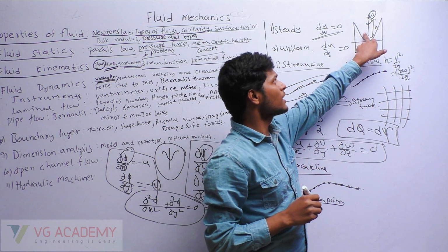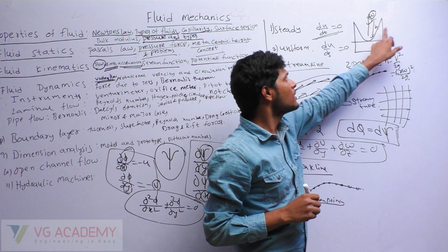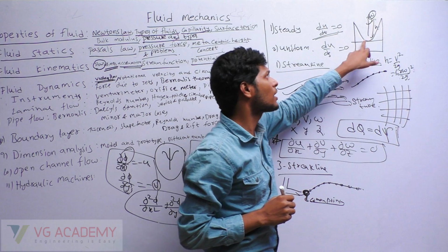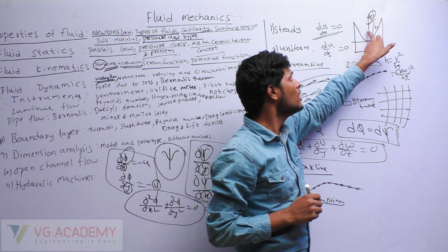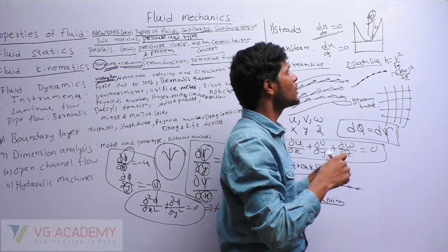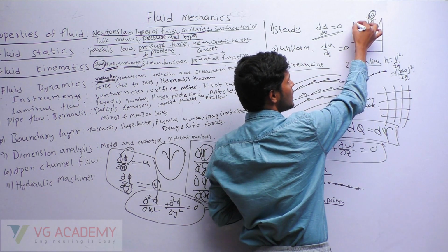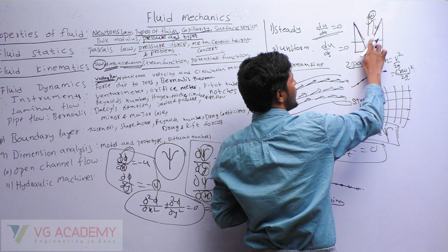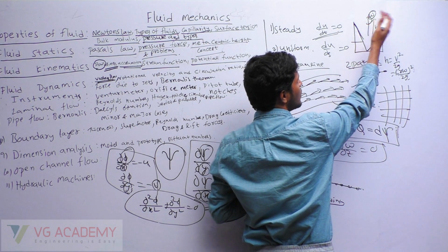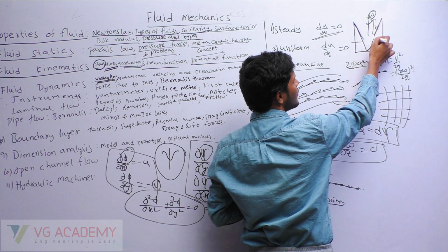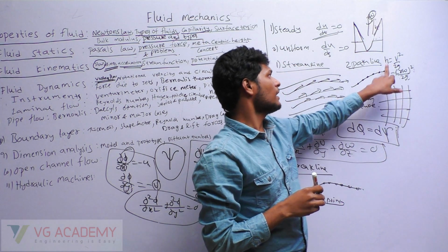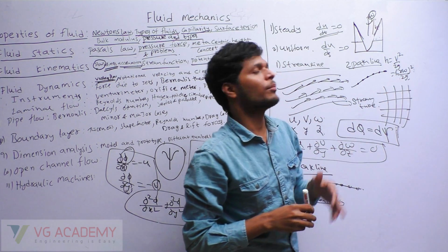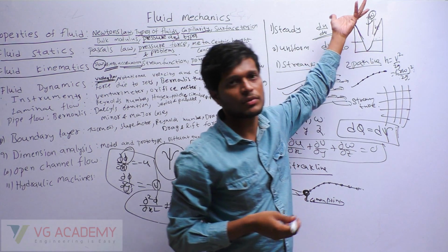Here, the volume of the water that will go out is half of the cylinder. This is a parabola curve, and half of the water will go out. So when you increase the velocity continuously, at most half of the bucket's water can go outside. The remaining water will never go outside. You can calculate the height using this formula: (r ω) whole square divided by 2g, where the maximum height is the height of the bucket.